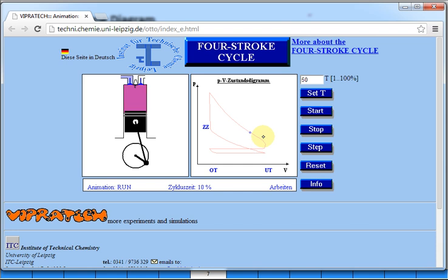A lot of exhaust goes down in the blowdown. Right now it'll be a big rush when that cracks open. Boom, right? Especially for engines under a load. You have a higher delta P right there. It's Mach 1. It's loud. That's why you have mufflers. And then it's above atmospheric pressure as it pushes it out through the exhaust manifold, catalytic converter, muffler, tailpipe, and then finally out. Yes?